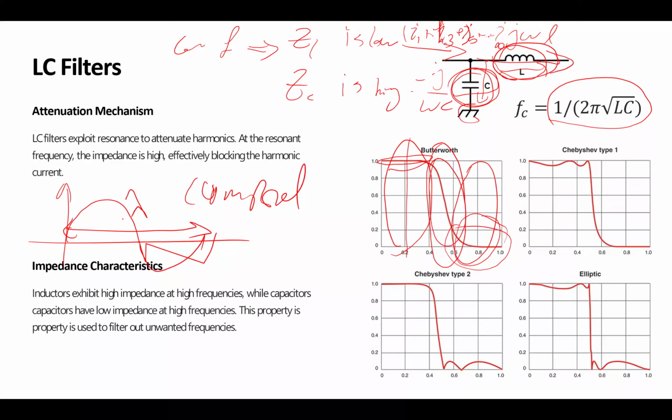For example, a regular inductor is 1 centimeter by 1 centimeter in physical dimension. If you put in a gigahertz or megahertz signal, because the wavelength is much shorter than 1 centimeter, then the lumped model doesn't work. KCL and KVL don't work. Ohm's law needs a kind of amendment.